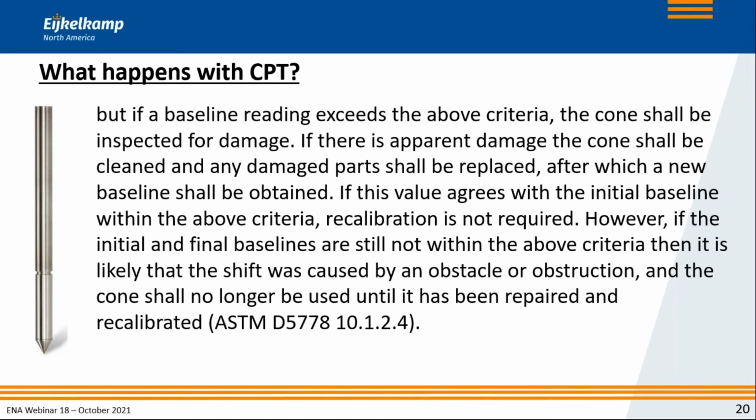So now suddenly we go back to mandatory requirements. And if there's apparent damage, the cone shall be cleaned and damaged parts shall be replaced. So suddenly, once those baseline readings don't meet the requirements, we again go back to what we expect from the standard, very mandatory statements. This shall be done, that shall be done.